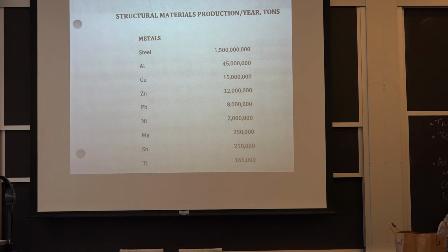Anyway, the aircraft carrier gains 250 tons a year, and they needed to make it lighter weight because it was going to cost them $50 million to design a new hull. So around 2000, they gave a $1 million contract to Newport News Shipbuilding to do a feasibility study of what if they used a 65 KSI strength steel rather than a 36 KSI steel or 50 KSI steel, which was traditional in shipbuilding. What if they went to a higher strength steel? How much weight could they save and what would be the total savings?